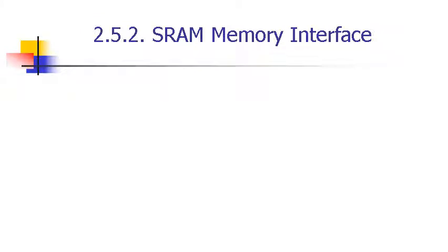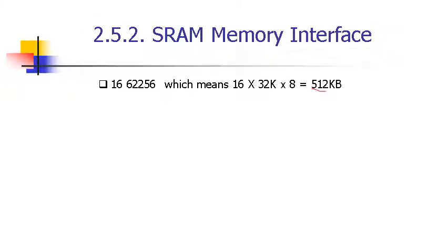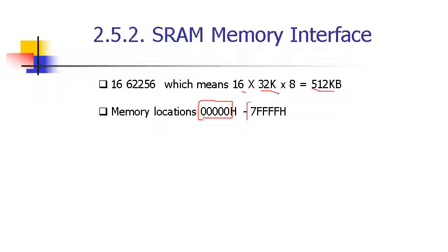Good. Again, this is 512, 32 times 16. Okay. This is your address range from 20 zeros to 19 ones. We have F, F, F, F. 4 by 4 is 16, and this 7 gives you 3 additional ones, so 19 ones.